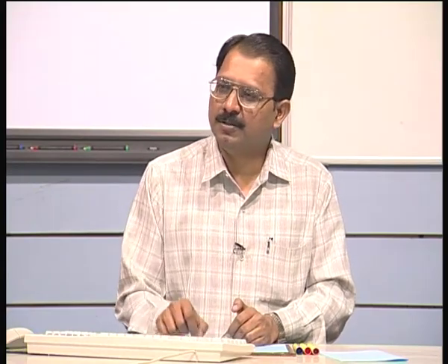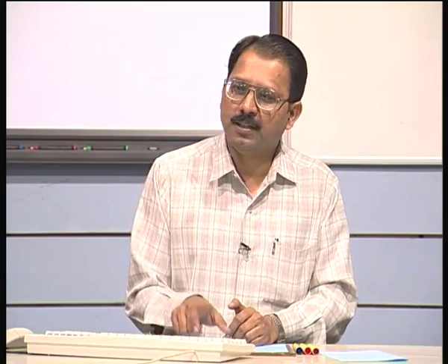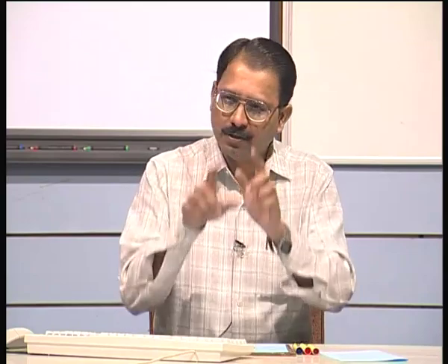Then I take, let us say, face 1. Face 1 is made up of 4 edges, let us say E1, E2, E3, E4. One of the edges is made up of 2 vertices, let me call them V1 and V2. So I will store this complete information in one place. Somewhere at the end or at another place, I will store the coordinates, the 8 coordinates of the points which give me an object like this.